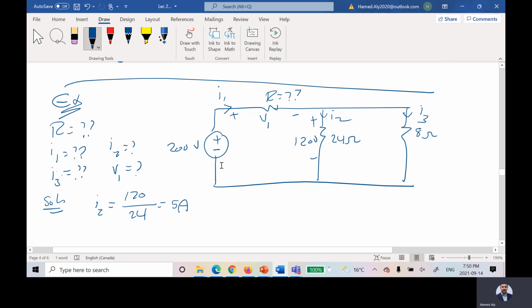You give me this voltage, and you give me this voltage. Can I find this voltage? Yes, the summation of the voltages for that loop is equal to 0. See? I'm trying to figure out how to solve the problem. But you can write the equations, that's okay, and you will solve the problem as well. But if you think, it will minimize the number of equations and the number of unknowns and will save your time. So I will say the summation of the voltages for loop number 1 is equal to 0.